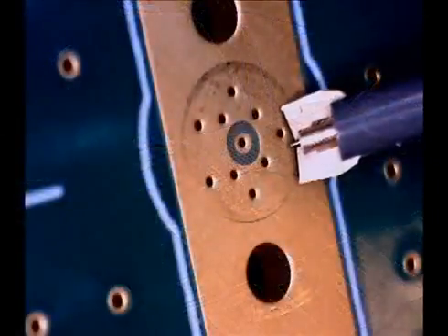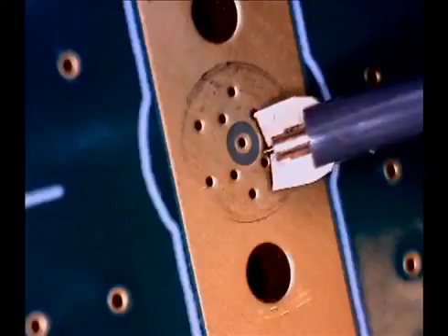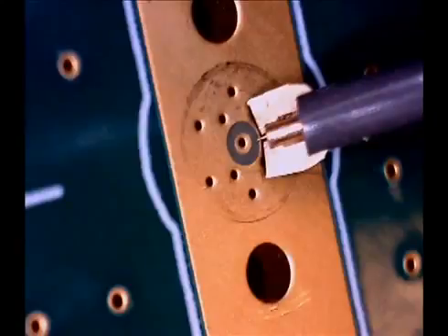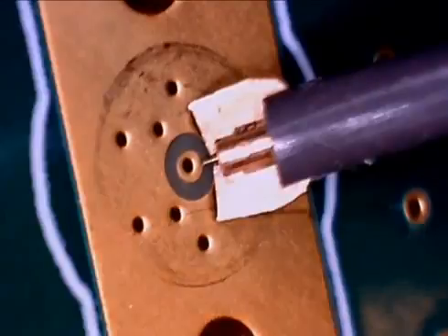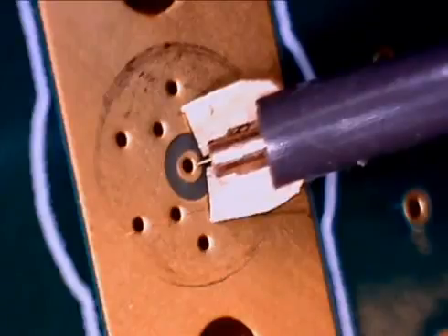Here we demonstrate the skill required for landing the microcoaxial probe with 1 millimeter spacing between the tip of the ground wings and the signal pins. As the probe is lowered to the clean PCB surface, one watches for the shadow to meet with the probe tips. As the probe gets close to the PCB surface, final adjustment of the X and Y positioning can be done. Then very slowly the probe is lowered another 1/4 to half turn on the controls, and a slight forward sliding motion is visible as the probe makes contact.